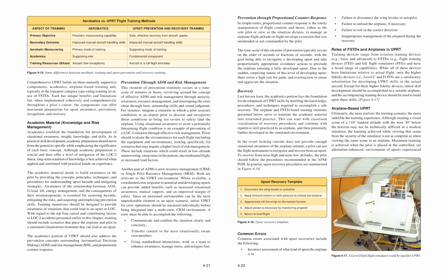Another part of ADM is crew resource management, CRM, or single pilot resource management, SRM. Both are relevant to the UPRT environment. When available, a coordinated crew response to potential and developing upsets can provide added benefits such as increased situational awareness, mutual support, and an improved margin of safety. Since an untrained crew member can be the most unpredictable element in an upset scenario, initial UPRT for crew operations should be mastered individually before being integrated into a multi-crew, CRM environment.